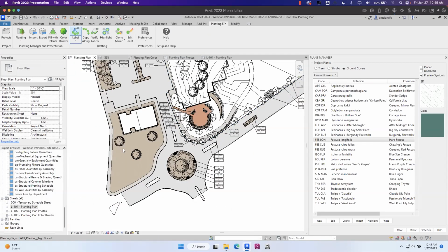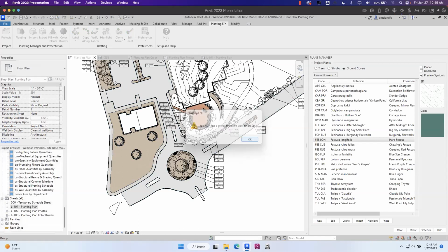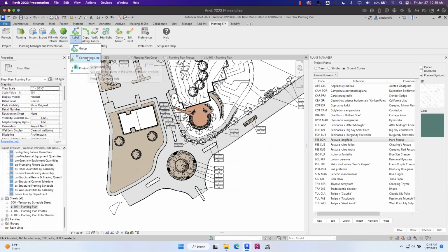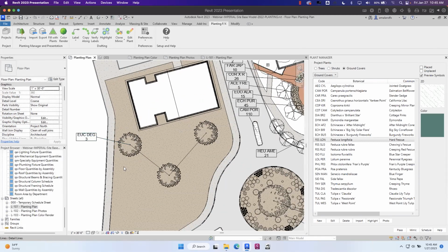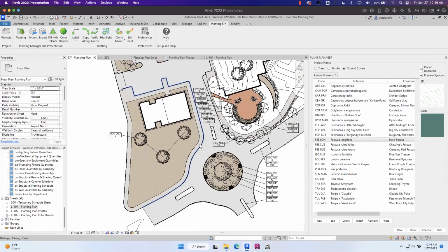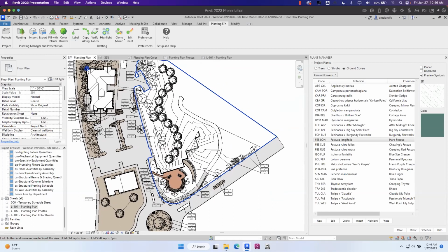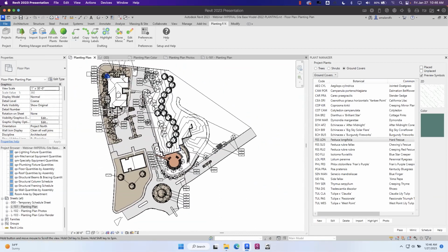And we'll grab these three, label, grab it, square over all of it. Actually, in this one, I'm going to escape. I'm going to show you connecting lines. So I can select this one, and then this one, and then this one, and then escape and place down the label, and I've got a connecting line label. Isn't that cool? Now you can edit any of these labels by going back to group label, and instead of selecting a plant, you select a label, and you can edit what these labels are counting. So that's one tool.